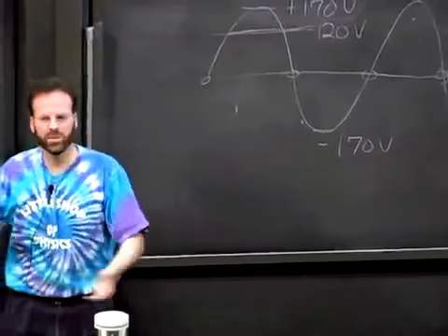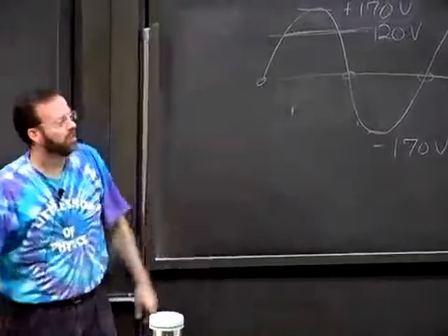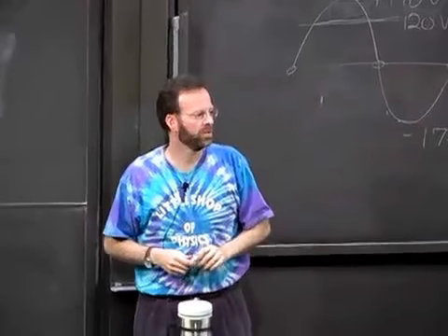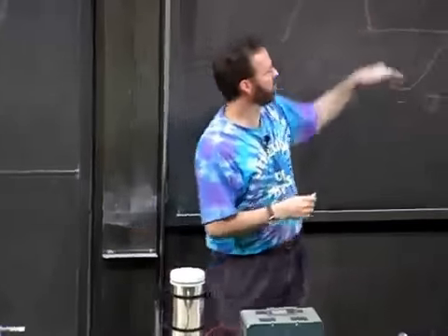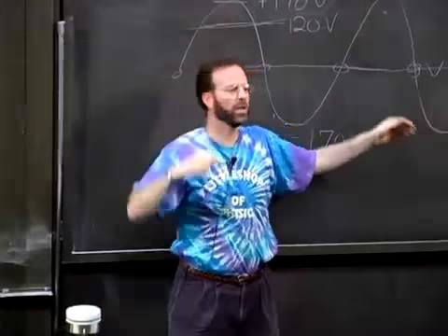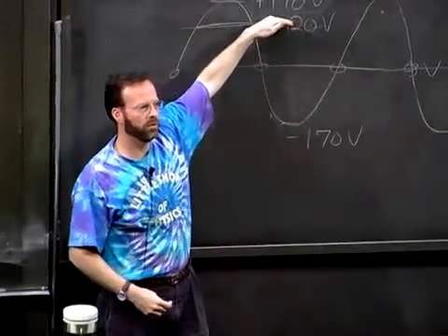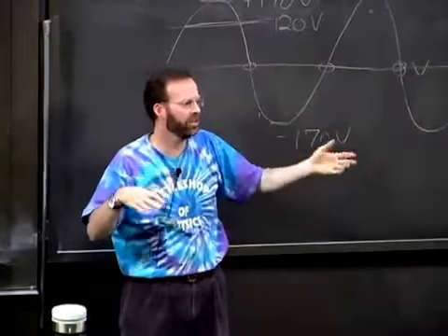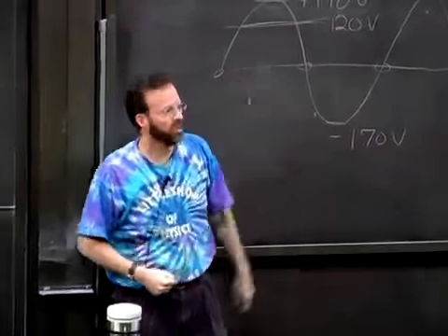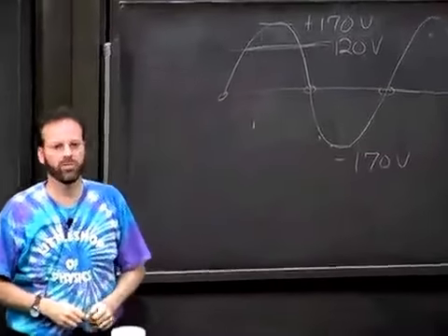So that everything else I've been teaching you in Ohm's Law, that's the number you can use, and it works out so that there's no discrepancies. Because if it's changing all the time, which value do you plug in? Oh, you plug in this root mean squared, which is kind of like an average that's useful for us. And that's how we can figure out all our circuitry and electronic problems.